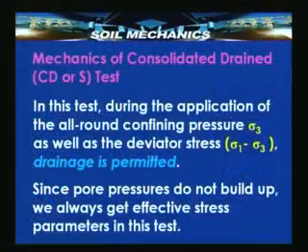Let us take the consolidated drained test first. The mechanics of the consolidated drained test is very simple. In the first stage of loading, that is application of confinement, drainage is permitted, and then in the second stage, when shear stress is applied, volume change is permitted. That means in effect drainage is allowed.